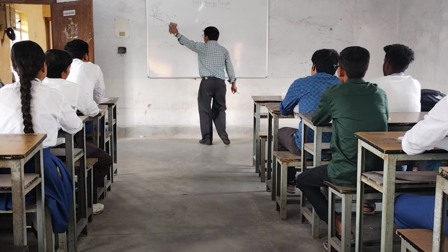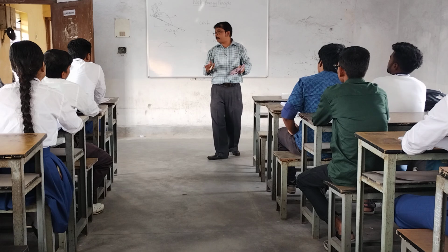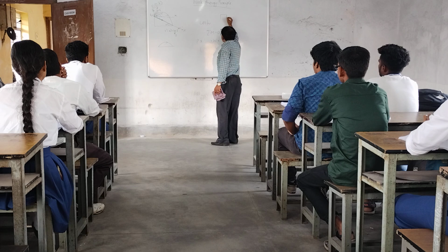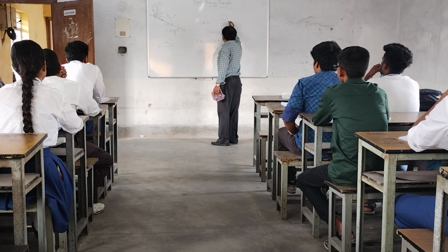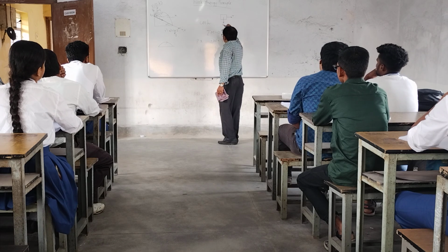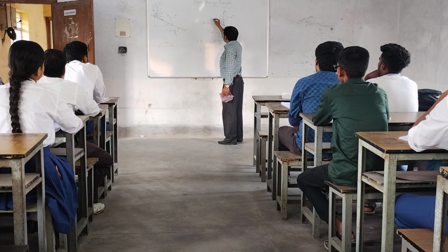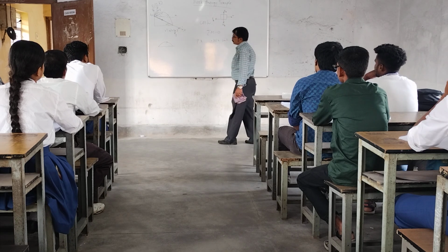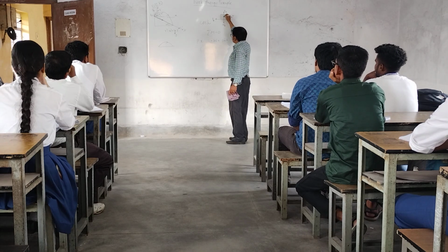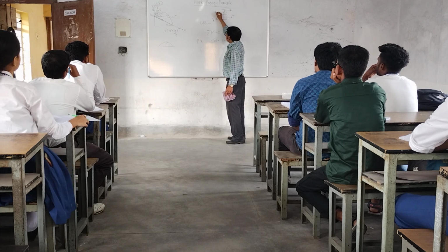You should solve those problems because this is a very common type of problem. And in the second problem, you have not drawn the free body diagram separately, most of you. So here there was a free body diagram: on this side tension T, here W for the weight of the mass, the body is here, so RA, and after that many of you have forgotten to give the frictional force FA. Now when you have drawn this free body diagram, it is placed on the horizontal surface and moving in this direction, so the inertial force is drawn in this direction.